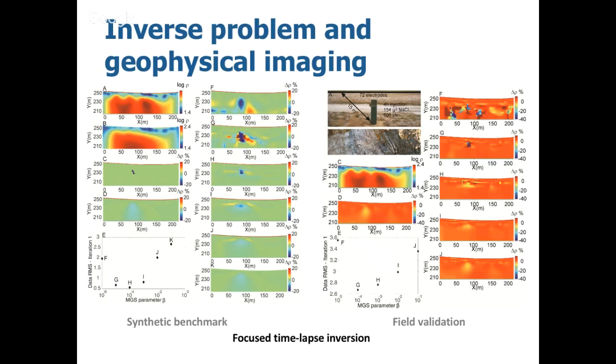So we used a field test, and we also validated the approach with synthetic modeling. This is the field test. The image is pretty dark, but you have a borehole here, in a fractured aquifer. It's fractured limestone, so you would normally see a plain limestone and a fractured limestone here. We injected a salt tracer for about 4 hours at 15 to 20 meters depth. We recorded a line perpendicular to the flow, about 15 meters away, and the line is about 200 meters long to make sure we captured the tracer. This was the work done by my first PhD student, Tanguy Robert.